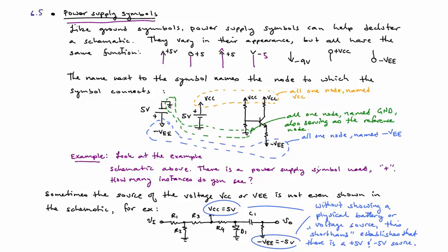These are different symbols, and you'll typically have something like +5 or +9, -10, or you'll have symbols like VCC, VEE, VDD, VSS. There's some history as to why those symbols have those names, but you will see those commonly used for power supply rails.